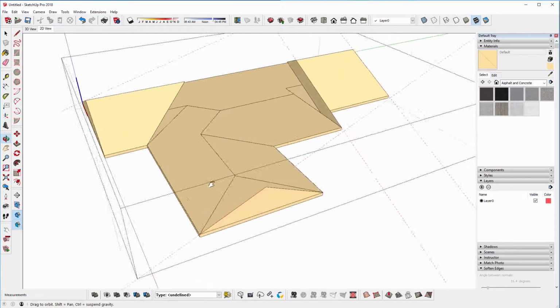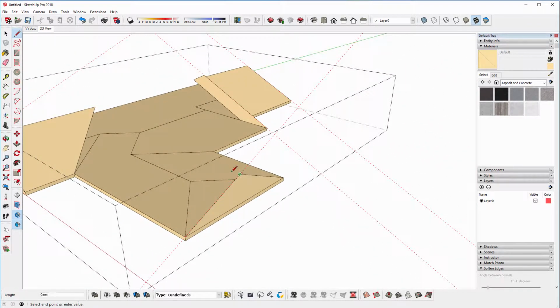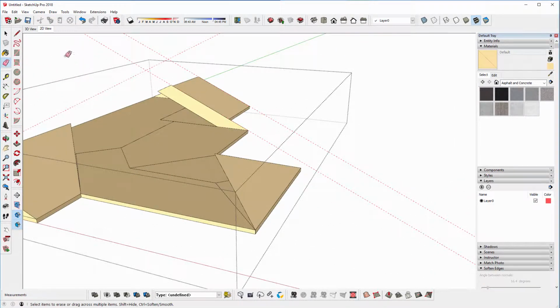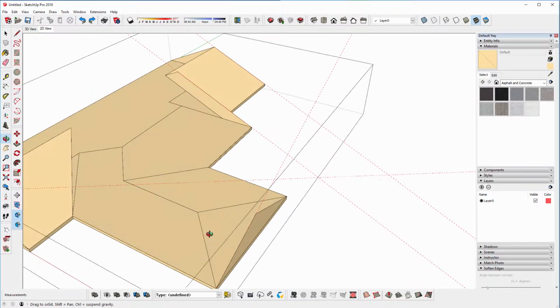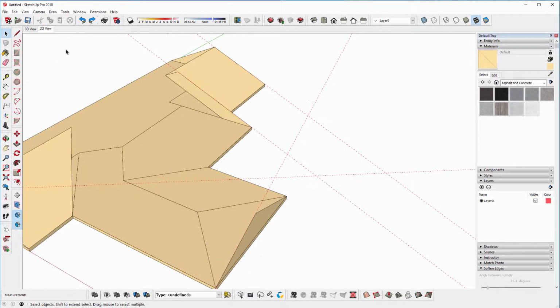This one here, there's two ways I could do it. I could either just draw a line back and then find the point here using the right arrow and then draw down to create the hip, and then I could just easily delete the lines and the construction line, leaving the hip. So that's one way, which is a solid way of doing it. However, another way is that you just get the select tool, click in white space but within the group, don't close the group. See how I accidentally lost my dotted lines around it?